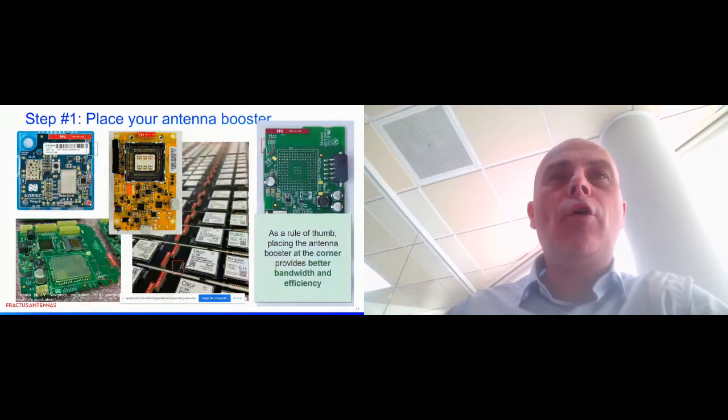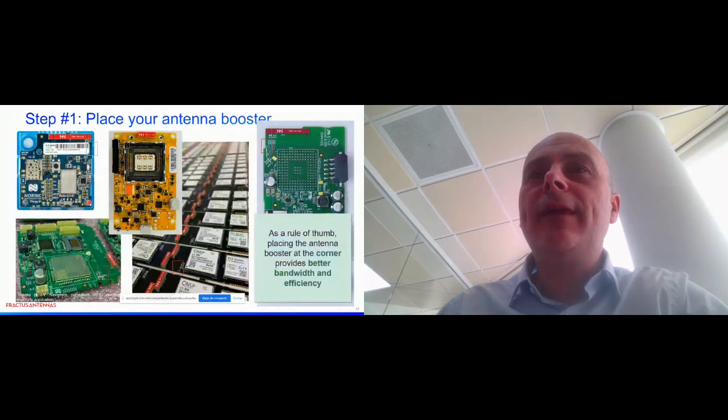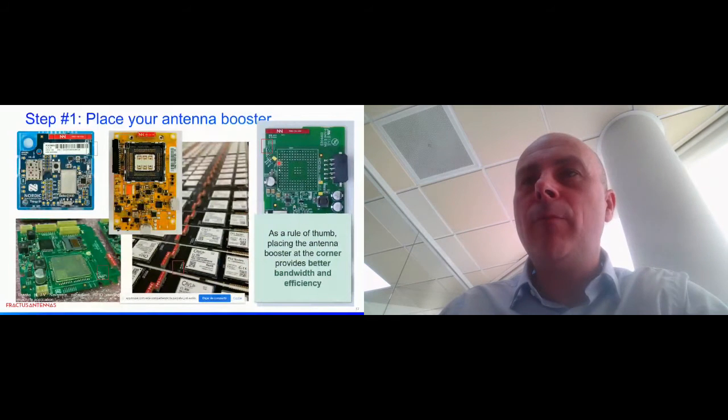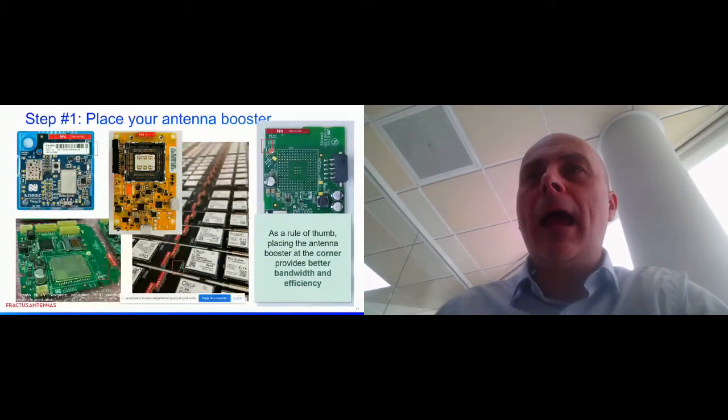This is the Mango Yellow by Sierra Wireless. As you can see here, the feeding line goes to the corner of the PCB. And with more detail, again, the Trio, the feeding line, and in here, between the module, which has been removed in this picture, and the antenna booster, we have a matching network. In this case, it's again for multi-band IoT applications.